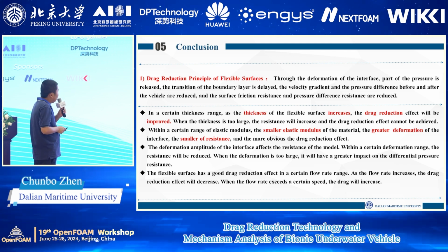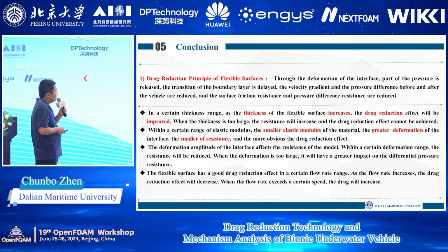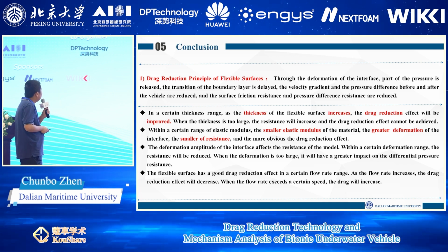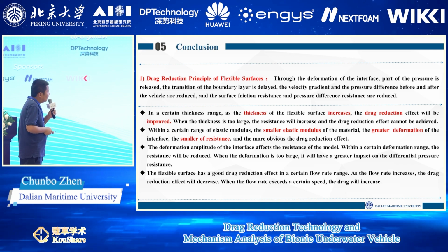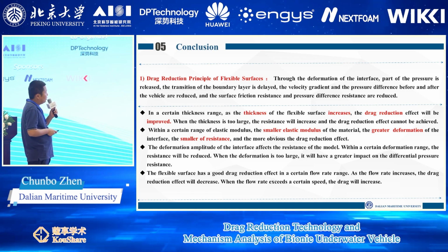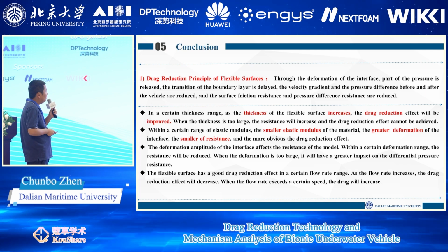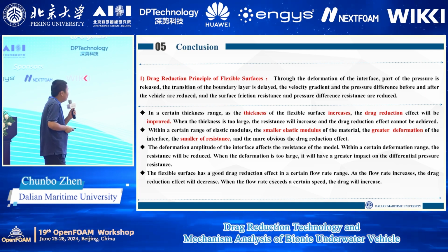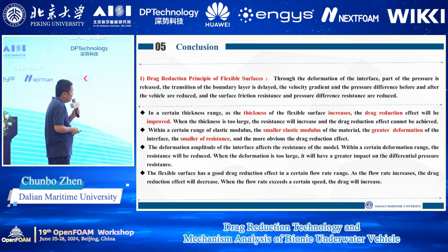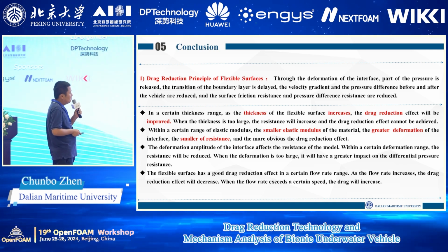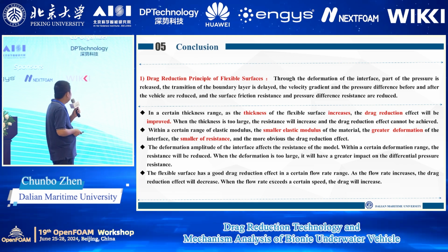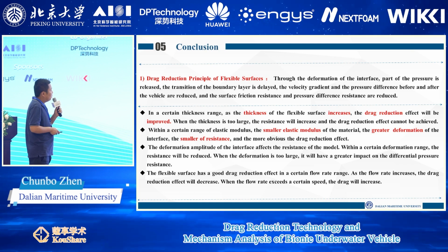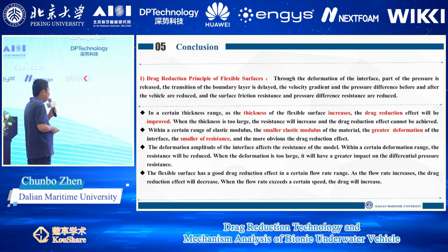In a certain thickness range, as the thickness of the flexible surface increases, the drag reduction effect will be improved. When the thickness is too large, the resistance will increase and the drag reduction effect cannot be achieved. Within a certain range of elastic modulus, the smaller the elastic modulus of the material, the greater the deformation of the interface, the smaller the resistance, and the more obvious the drag reduction effect.